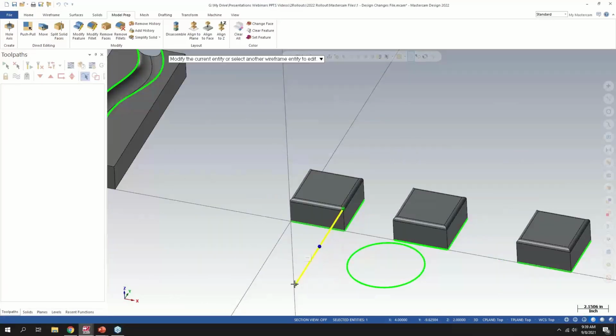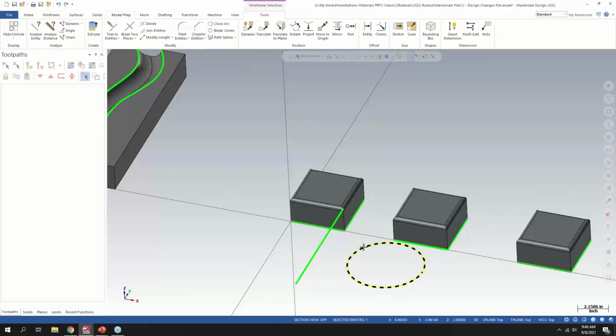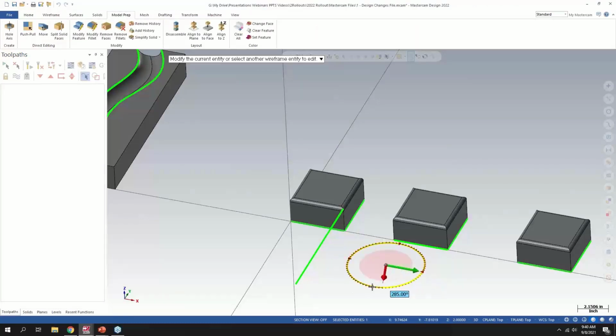It knows that it's now perpendicular to that axis. And then I also want to show how arcs work. So if I double click an arc here, I can modify the length or angle of the arc. If I go there in the positive direction, it will create that part of it. Or if I undo and do it again, I can go around this way and modify the arc that way. And there's also a flip option that pops up, so I can get the inverse.